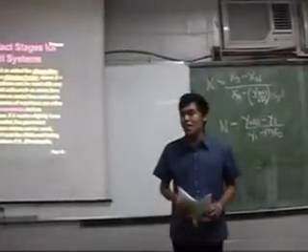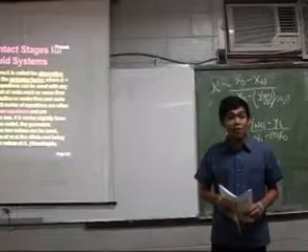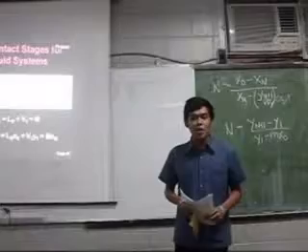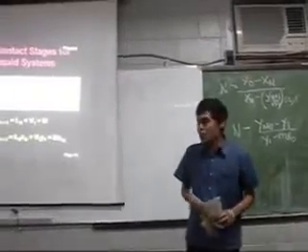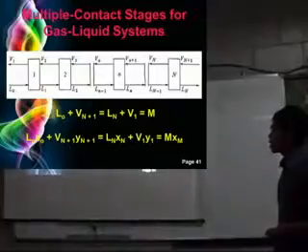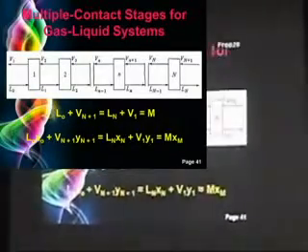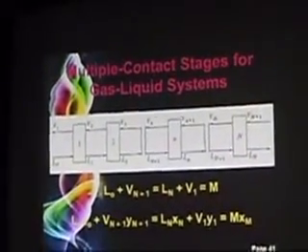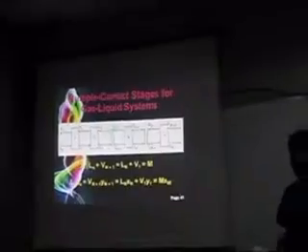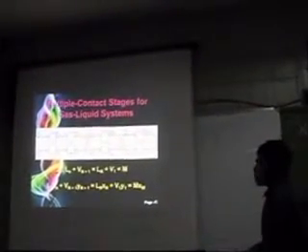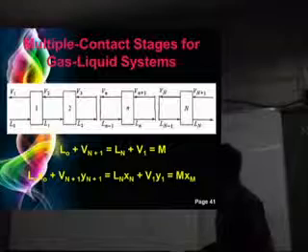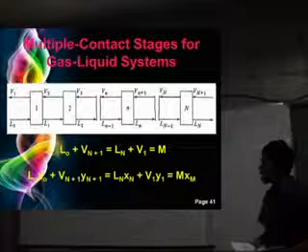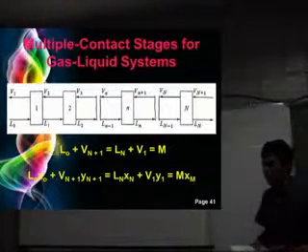So, classmates, before we go to the sample problems, you might be wondering what is the equation for the operating line. So let me go back to the overall mass balance. From the multiple cascades, we have L0 + V(n+1) = Ln + V1, the streams being equal to the mixing point. For the component mass balance, we have L0 x0 + V(n+1) y(n+1) = Ln xn + V1 y1.